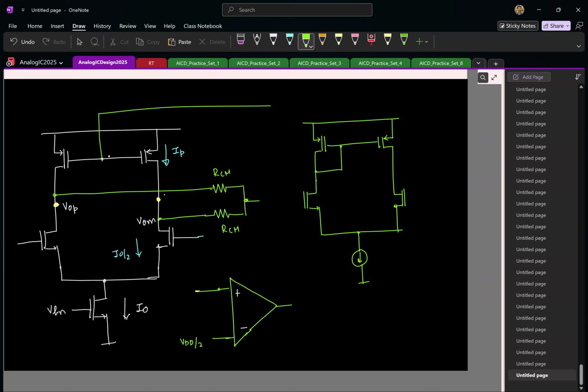So I make the diode connection here. This is going to be my output. So let me connect it back. The output of the op-amp controls the gate bias. Now I have the inputs. Let's figure out what should be connected where. If this is the output, what is the plus terminal, the left side or the right side? Left side, because remember, if I increase the gate voltage, what can you say about the drain voltage here? From gate to drain, there is always an inversion, right? So the right side is going to be negative, left side is positive.